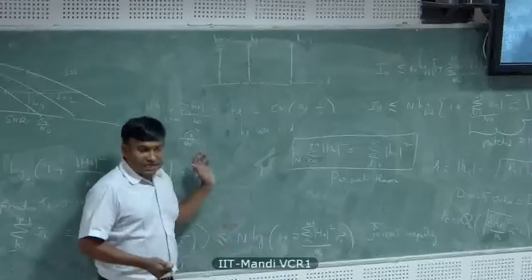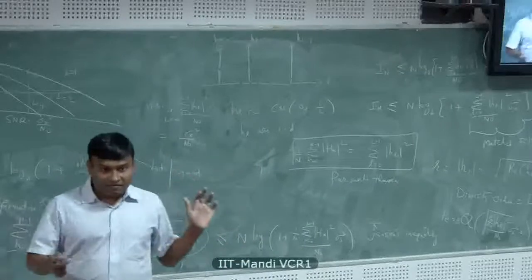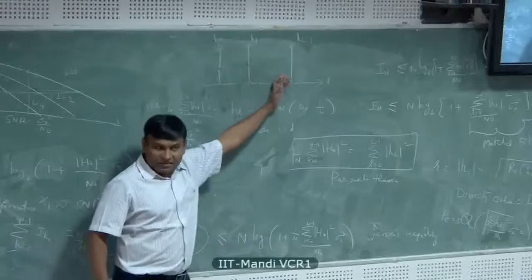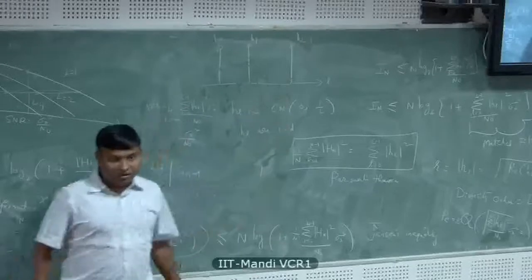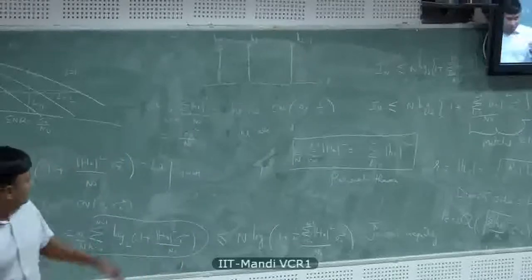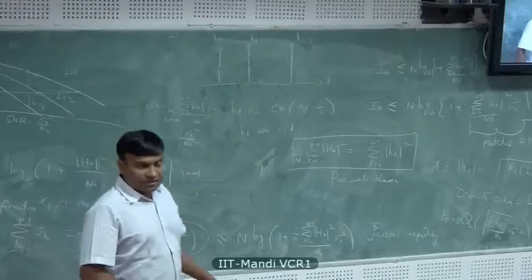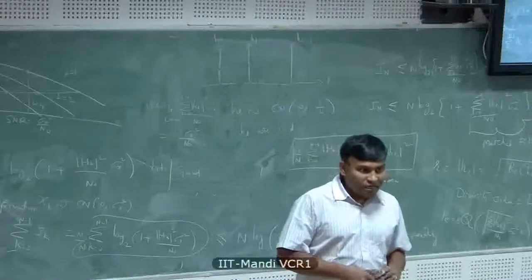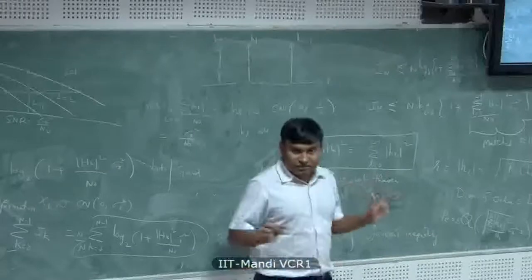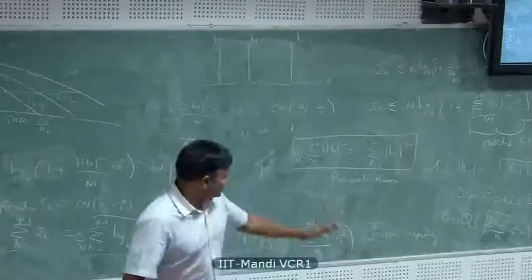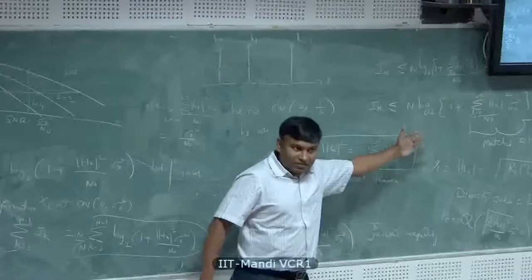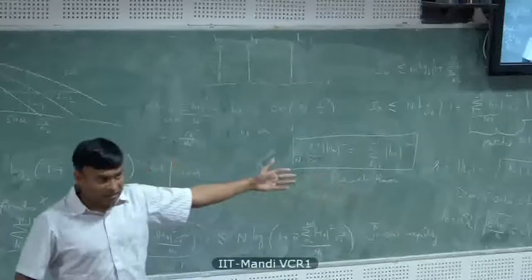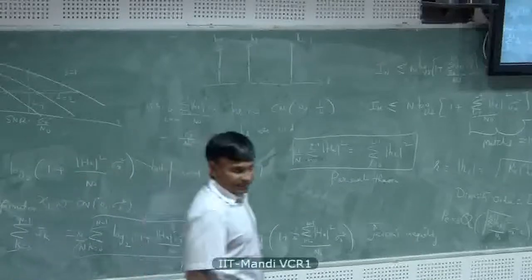Whereas broadband systems like OFDM, with very high bandwidths, you can resolve the multipath taps into fine resolutions, and then you get plenty of multipath components. And if you design the transmitter and receiver in a clever way, you can exploit this diversity. Well, we haven't taught you yet how to exploit this diversity. This is just a bound we're talking about, the best that you can probably achieve, and you probably won't reach that bound so easily.